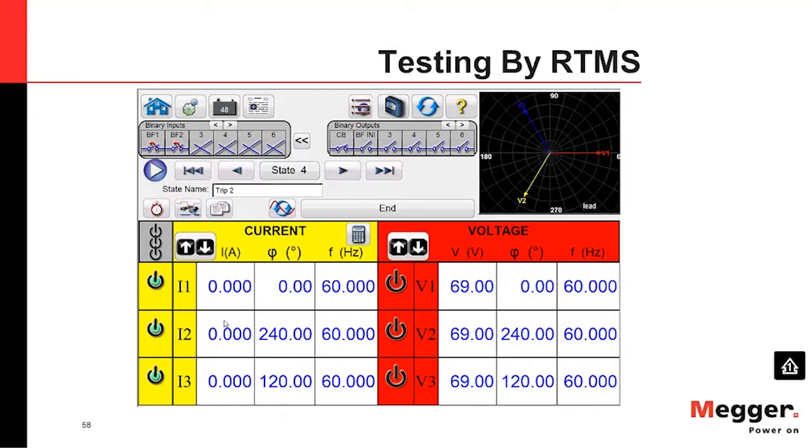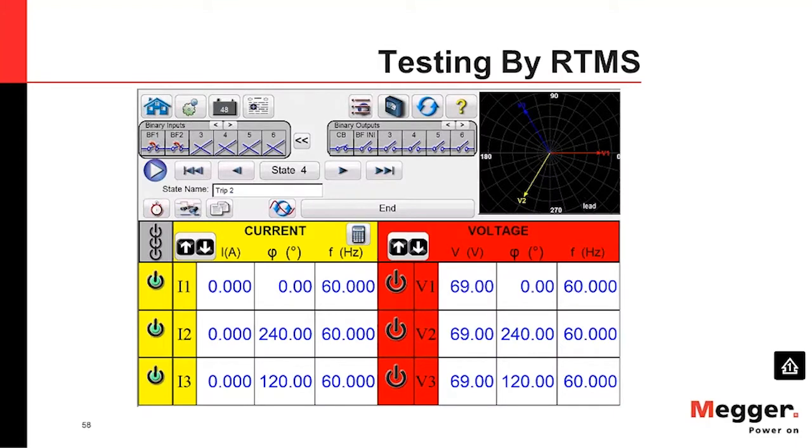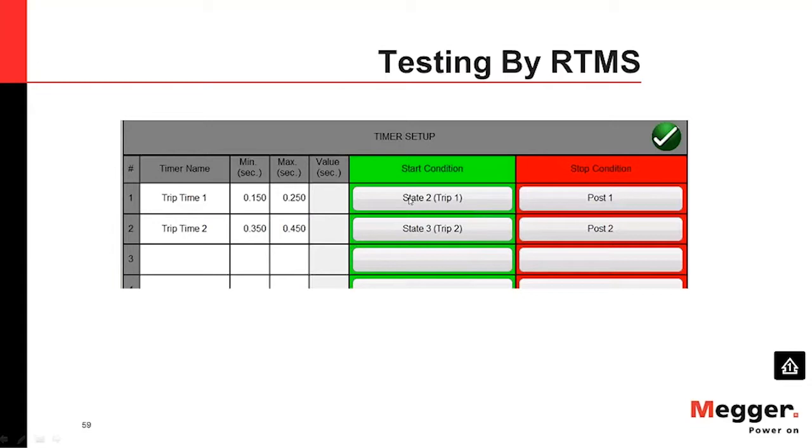How we are testing the breaker failure timing. The good thing here is that we will have 2 timers, of course. From the timer menu here, we can set up these 2 timers, like when we need to start and when we need to stop. So we'll have the correct timing over here.